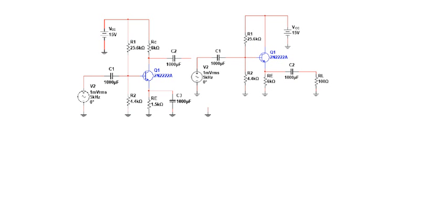We really don't need but one capacitor, but it'll be okay. This AC supply here, right in the middle, is that whole amplifier right there. And that load resistor we just covered up is whatever we see now looking into the front end of this amplifier. So what do we see looking into the front end of that amplifier? Well, I'll show you. We're going to see those two resistors, R1 and R2, in parallel. Remember, they got in parallel when we did the AC equivalent circuit.